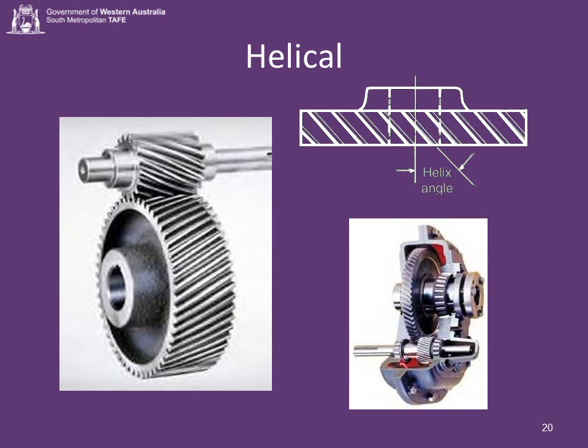Helical gears are designed for parallel shaft operations, like the pair shown. They are similar to spur gears, except that the teeth are cut at an angle to the center line. The principal advantage of this design is the quiet, smooth action that results from the sliding contact of the meshing teeth. A disadvantage, however, is higher friction and wear that accompanies the sliding action. The angle at which the gear teeth are cut is called the helix angle.